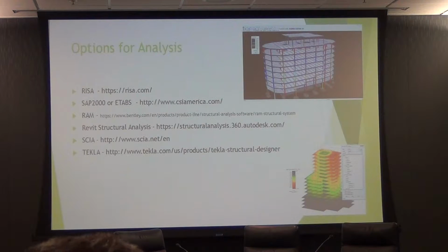Hey Paul, is this Revit Structural Analysis the same thing as Robot? No. Revit Structural Analysis is actually an Autodesk 360 cloud design option where you upload your Revit model or some exported version of that to the cloud in A360. It does whatever analysis it's going to do and then pulls it back into Revit. And I believe that somehow through the add-in that they have, it does things like show your deflections and stresses and things like that in the model. But like I said, I found it to be pretty cumbersome.